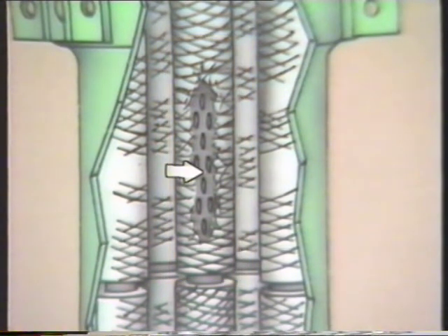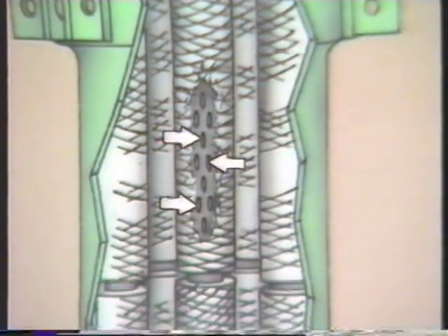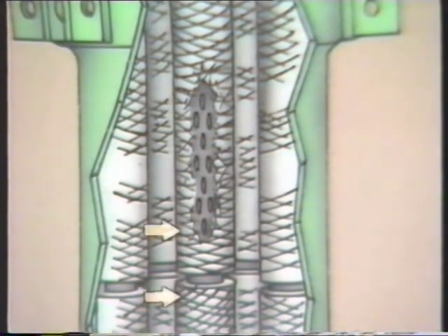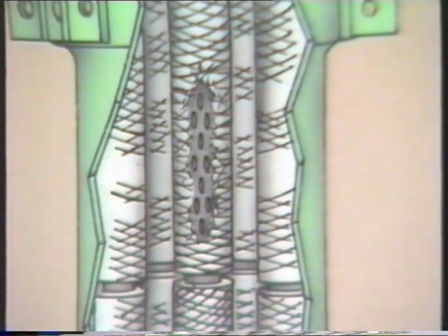This center core is a hollow shaft made of metal or plastic. The core is pierced with holes to allow the liquid to pass through it. The spacer seals the center core between two connecting filter tubes. The spacer prevents unfiltered liquid from bypassing the filter medium and leaking directly into the center core.